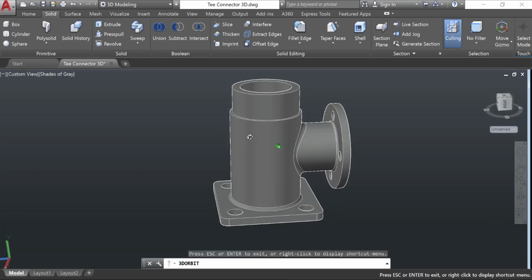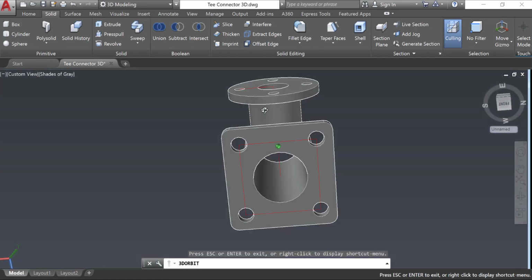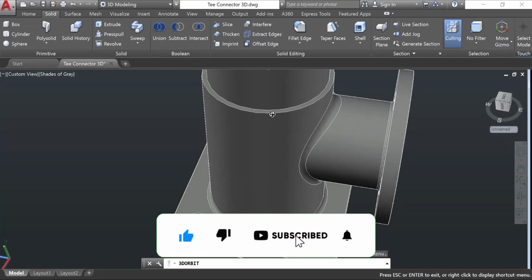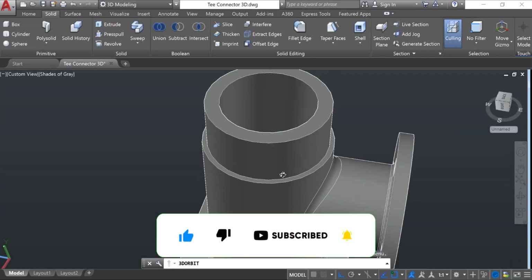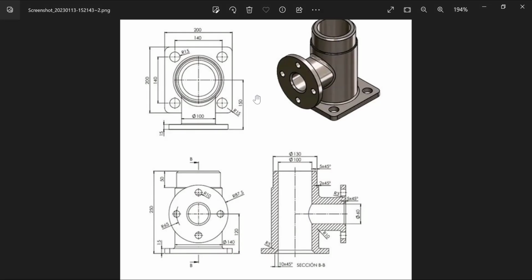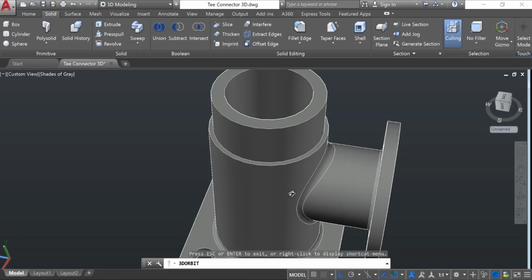Chamfers have to be over here, and over here, and over there. This edge, and also this edge. So where do we start? This open one. The edge here above is 5. This one is 5 at 45. So the tangent of 45 is 5 by 5, which is equal to 1.